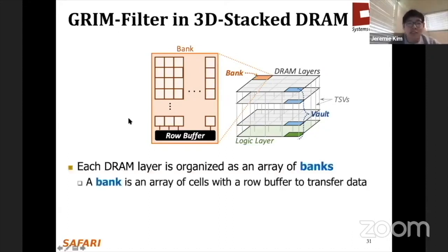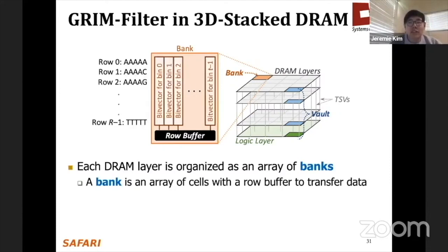We now show the distribution of bit vectors across the DRAM arrays to enable parallel processing of the bins. Each row represents a token's occurrence across many sequential bins, and the row of the appropriate token gets queried to find a vector showing the occurrence of the token across many bins. These are the vectors that are brought down into the logic layer to be operated on.